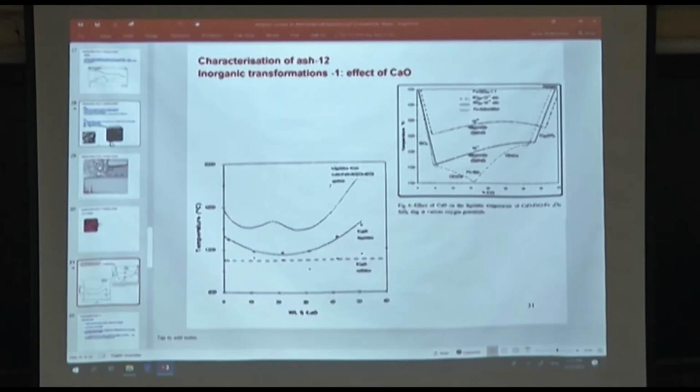So, you can actually take a sample of silicon oxide, aluminum oxide, iron oxide, calcium oxide, magnesium oxide, and say sodium carbonate. You mix them in certain proportions, then another proportion, and another, and melt them in the ash fusion furnace, as I showed the other day, those cones. You will see they all melt at distinctly different temperatures.